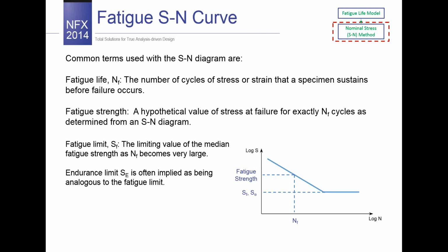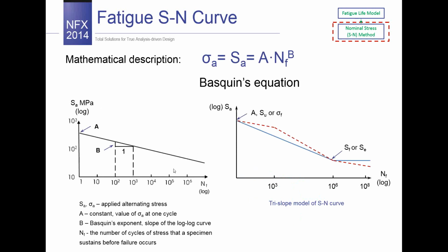Normal quality steels and low alloy steels have this asymptote. In this case, this is the maximum stress amplitude at which the specimen will not fail. And for materials where there is no asymptote, fatigue limit stress is defined at 10 to the power of 7 or 8 cycles. What is also important is that fatigue limit is a material constant, but depends on way of loading. For example, for pure bending it is 10 to 15% higher than for tension. And notches, mean stresses, environment, microstructure, surface finish, and temperature are important factors, and they have a big influence on endurance limit.